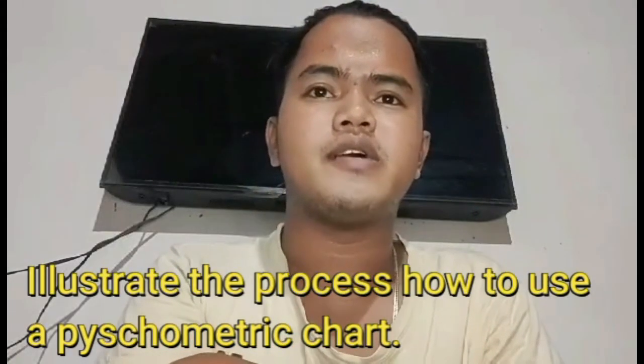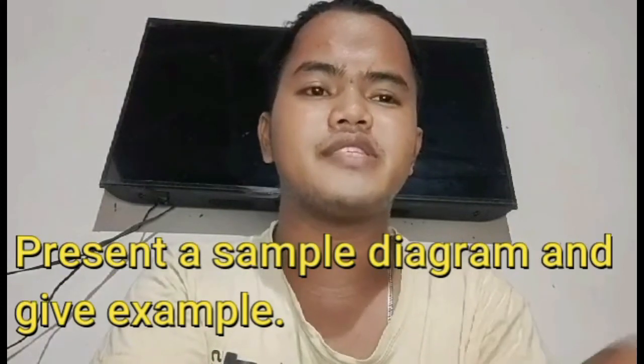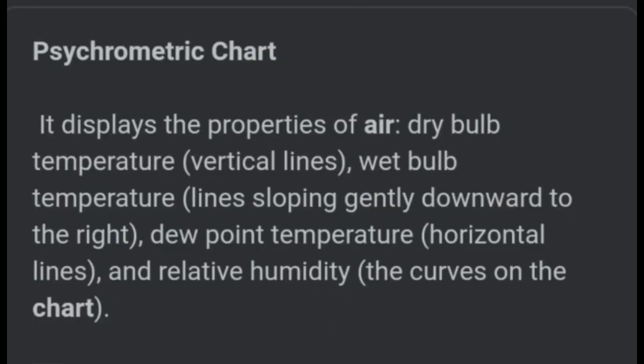Illustrate the process of how to use a psychrometric chart. Present a sample diagram and give an example. First, what is a psychrometric chart? It displays the properties of air: dry bulb temperature, vertical lines; wet bulb temperature, lines sloping gently downward to the right; dew point temperature, horizontal lines; and relative humidity, the curves on the chart.